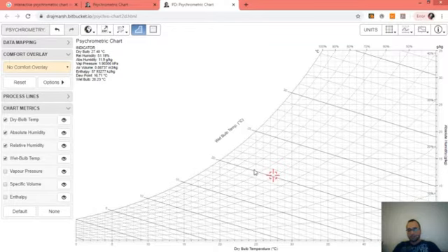The line that should be followed is this oblique line, and we can see that the air temperature drops. So the evaporative cooling process will cause absolute humidity to increase, relative humidity to increase, and the air temperature to decrease until the volume of air reaches saturation.